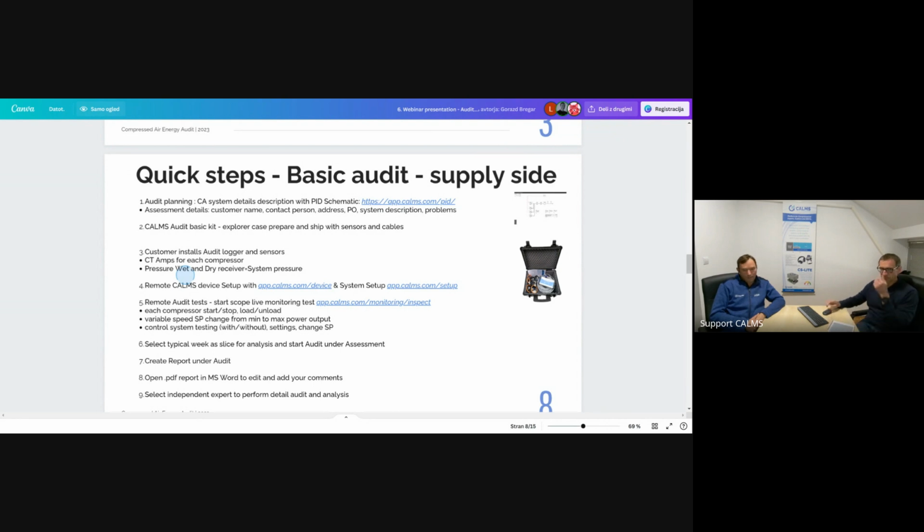The smelter house is closest to the compressor station. There we do not experience that many problems, but the further you get away from the compressor station, the more problems there are, and these problems are intermittent. They do not happen all the time. So it could be a possibility that one of the compressors is not giving 7 bar all the time. We should find which compressor is giving problems.